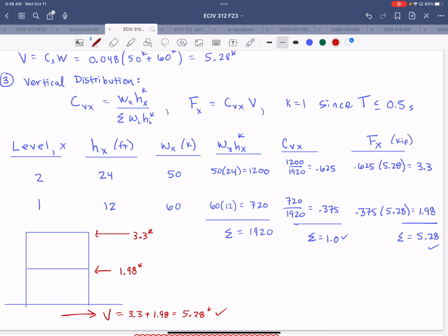And actually, I've been told this by someone who was on these committees, who knows the reason that there are height limits of like 160 feet or 250 is mostly arbitrary. It's a compromise between people who don't agree. So that's how they choose those height limits, based on how well a structural system is expected to perform in a certain high seismic region. But yes, in general, taller buildings tend to be more flexible and more ductile.